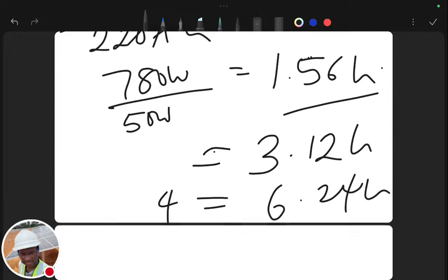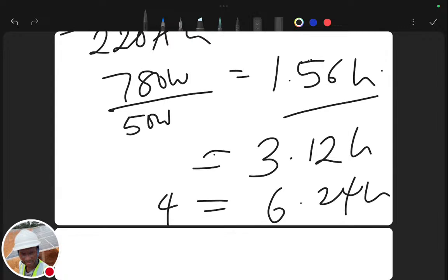If your customer can only afford 1 battery, you go for it and you let them understand that they are limited to 500 watts. They should use it during the day. They should use most of the heavy things during the day. Once it's night, they should minimize usage. Maybe use only 1 laptop, turn off the light, use fan. Don't turn on the light of the kitchen if you are not in the kitchen. So those are the kind of things you need to tell your customer.